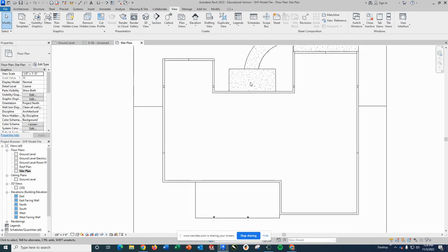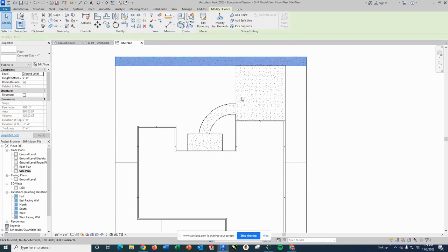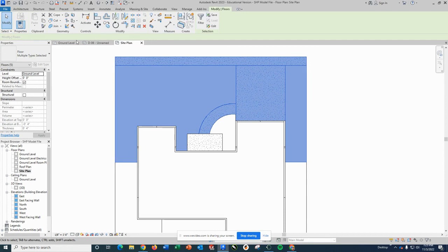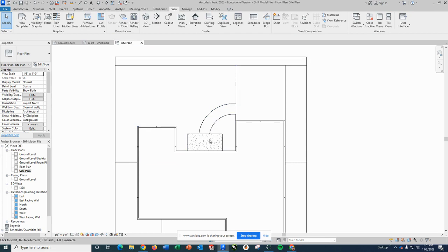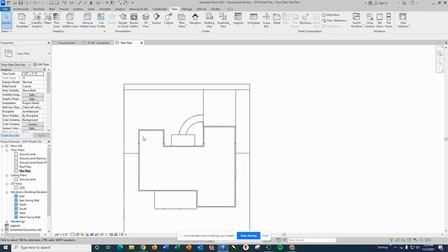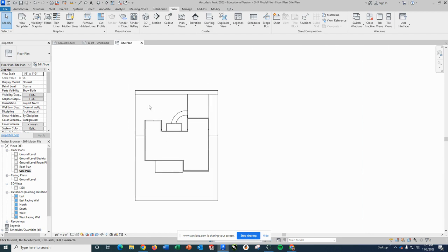The other thing to do would be some of these floors. So this one, and actually what you can do is you can use your drag tool and select them like this. And these are all floors, and if I change them to my grass floor, you'll notice I don't have a filled pattern anymore. I'm going to do that here as well to get those all as grass. And again, the inside ones, you can just hide those because you don't want it engraving a pattern. You want something very plain, very bland like this. This gives you the size and the location of everything.